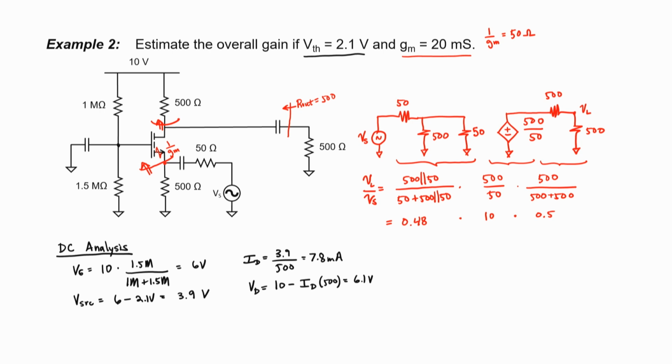Something that you might notice when you're looking at the common gate amplifiers and comparing them to, say, the common base amplifiers is that this middle number tends to be larger for bipolar transistors than for MOSFETs. And that's related to the fact that this little Re, or the emitter resistance of a bipolar transistor, tends to be smaller than this effective resistance, or 1 divided by Gm, that we're seeing here with MOSFETs.